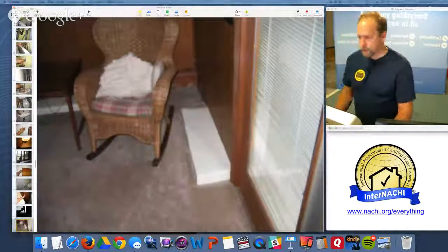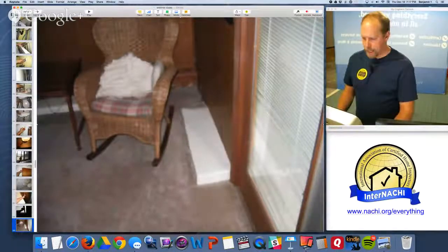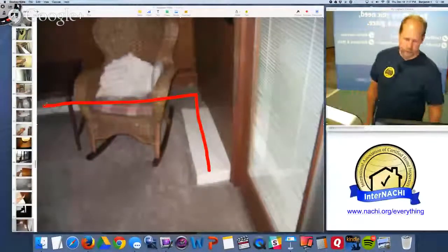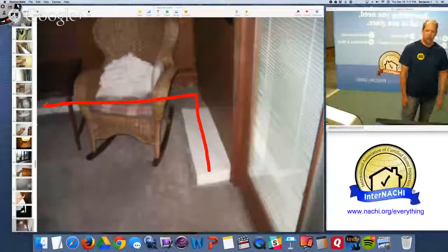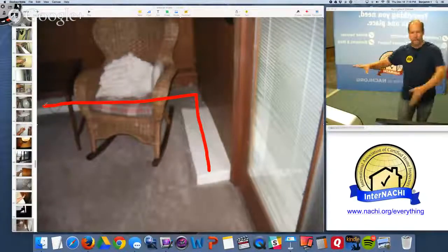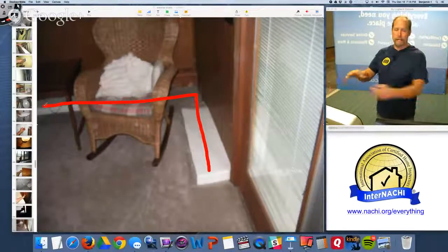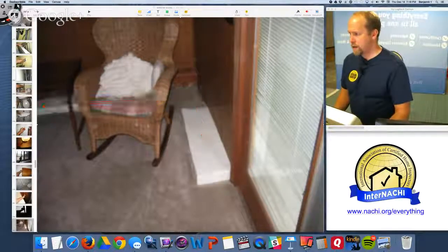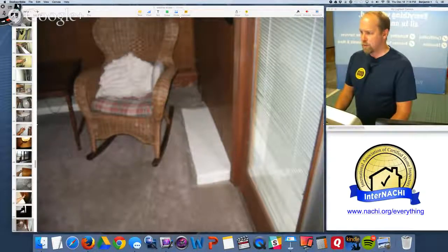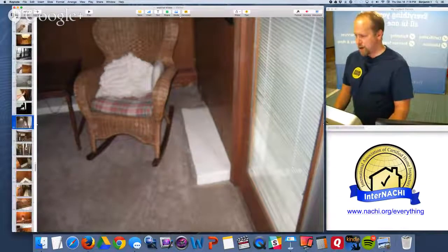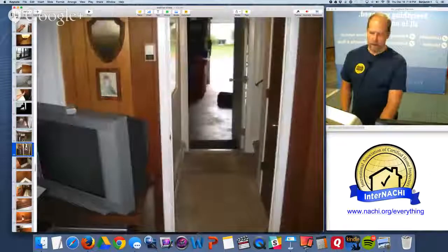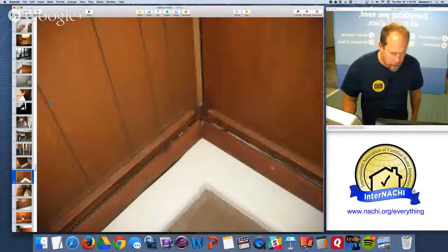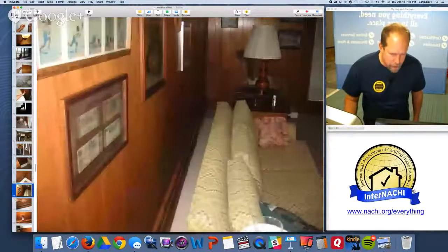See this in the basement. We're still in the basement here. And if you take a look, this is a perimeter French drainage system of some kind. That's a concrete block cover over a ditch, I'm assuming, with maybe some gravel and some pipe that leads all the way to the crawl space sump pump. Thought that was an interesting way of doing that. So my hunch that there are water problems with this house are pretty much confirmed because they installed that drainage system. But they have furniture and it's a finished basement. You know, it's living. Looks kind of white paint. Maybe they recently painted it.